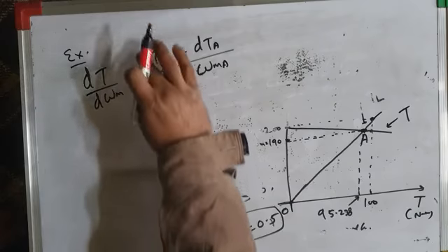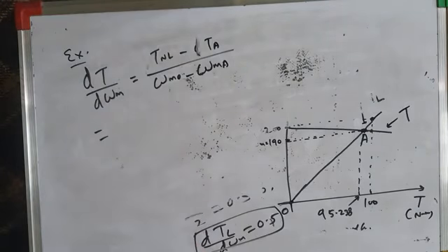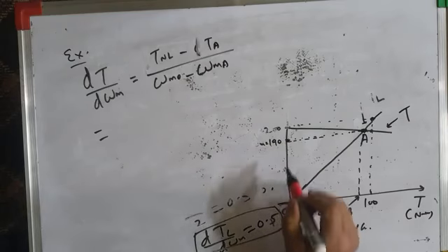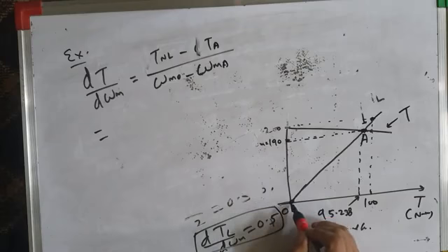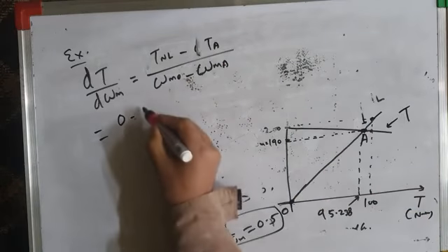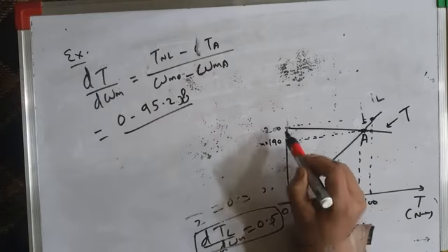So what is no load torque of the motor? When load torque is 0, motor also develops 0 torque here. At omega m equal to 0, torque, you can see torque is 0. 0 minus how much torque it is developing at A? It is 95.238.